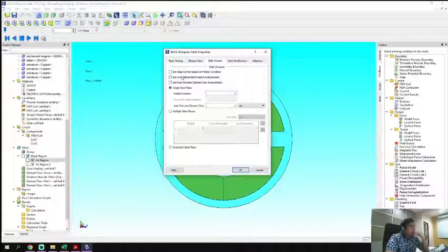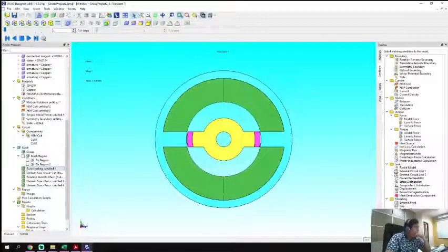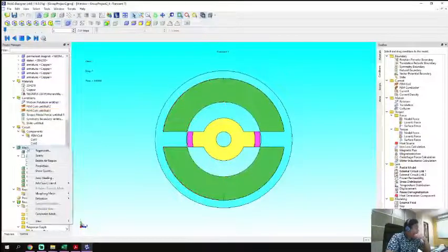And before that, I select the stack control based on motion condition. But when I generate the mesh, it unticks for me. I don't know why, but yeah. But this is the first that I do. I click both of them. I'm okay with that. I press OK, and then we create the face.